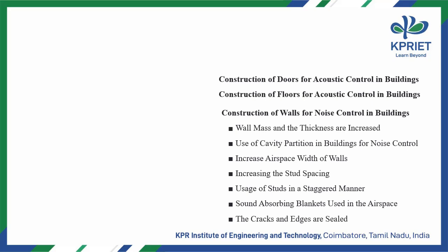Use of cavity partition in buildings for noise control. Increase airspace width of walls. Increasing the stud spacing. Usage of studs in a staggered manner. Sound absorbing blankets used in the airspace. The cracks and edges are sealed.